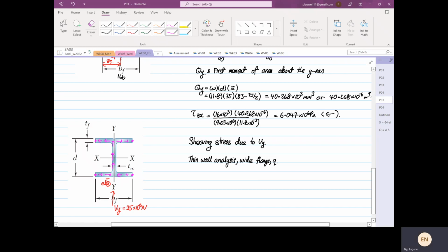Okay. So the area of interest now is this area. I will stop here and highlight in yellow. This is the area of interest. Okay, so the formula that we're going to apply is shear. The plane intersects the z-axis, the shear flow is going in x, and at point A this will be equal to Vy over Ixx, Qx divided by t.